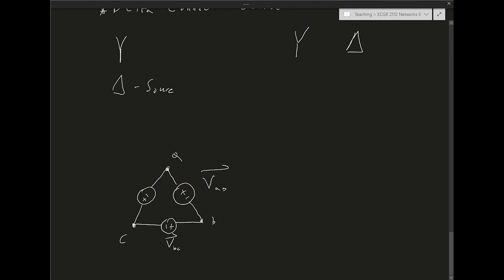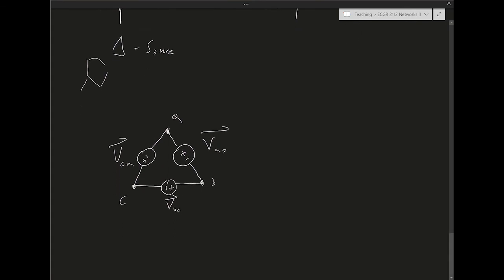And in a similar manner to loads, you really cannot tell by just measuring the voltages whether the sources are connected in delta or Y, right? Because when you measure the voltage between node A and B, it will be the same whether the load is connected Y or delta. You will get some voltage, right? So there is no way to distinguish between them other than by direct inspection. But what I'm trying to say is both are equivalent ways of supplying three-phase voltage, right?